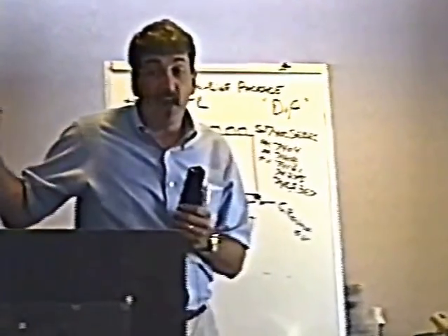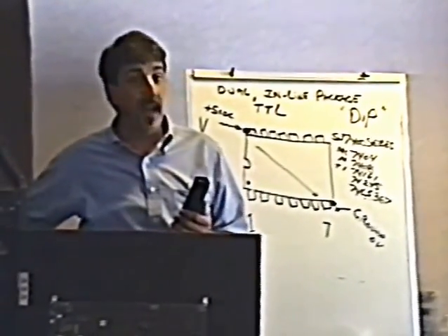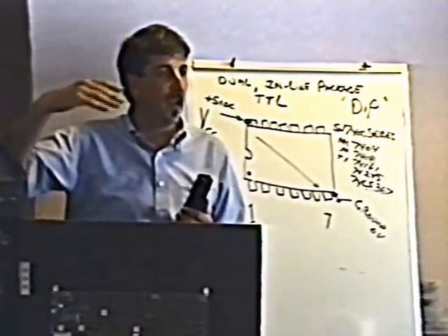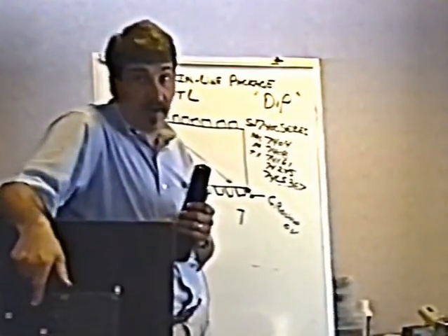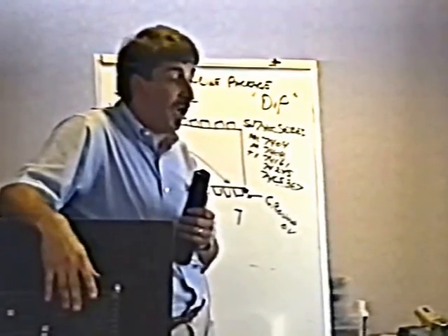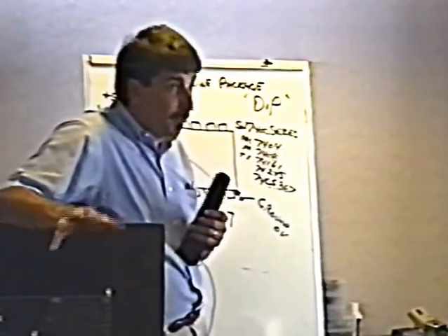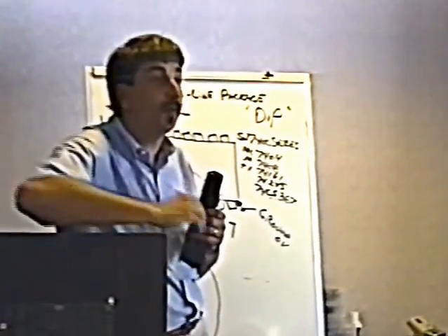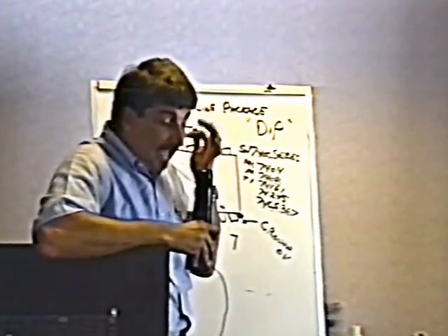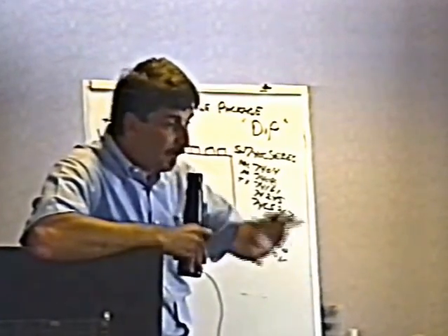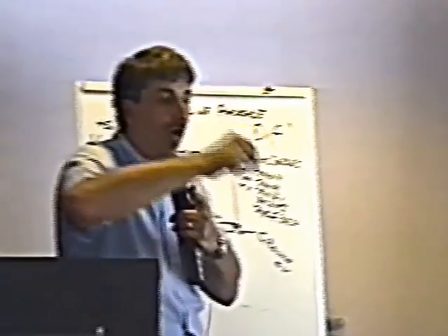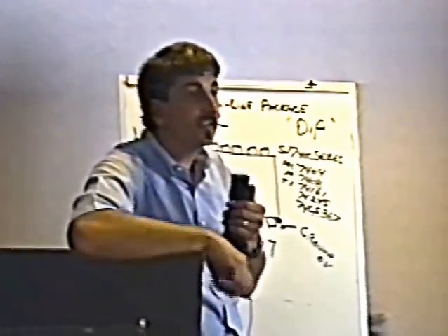Many games have a self-test in them. You've probably seen it. You fire up a game, it says ROM okay, RAM check, or whatever. If it tells you that one of those devices, one of those ROMs or something that's in a socket, is bad, it may be that, or it may be some other chip, but you certainly want to try that first. Another thing that you can do is to get another one of the same game and try swapping all the chips that are in sockets.